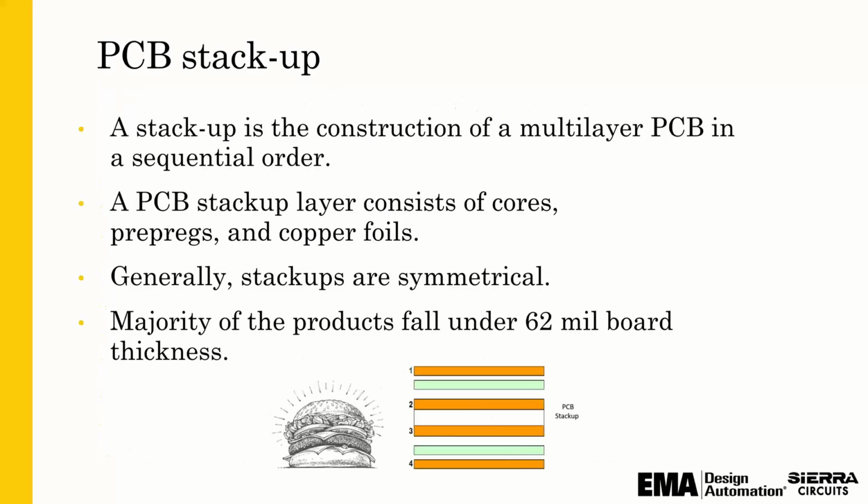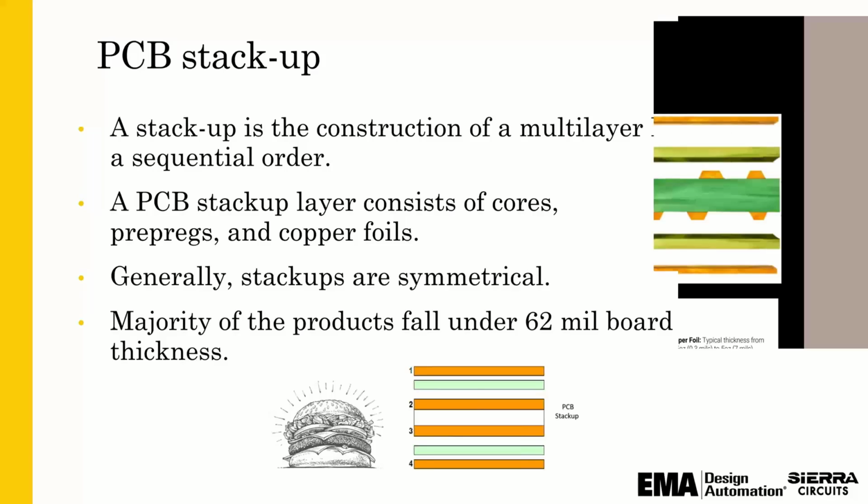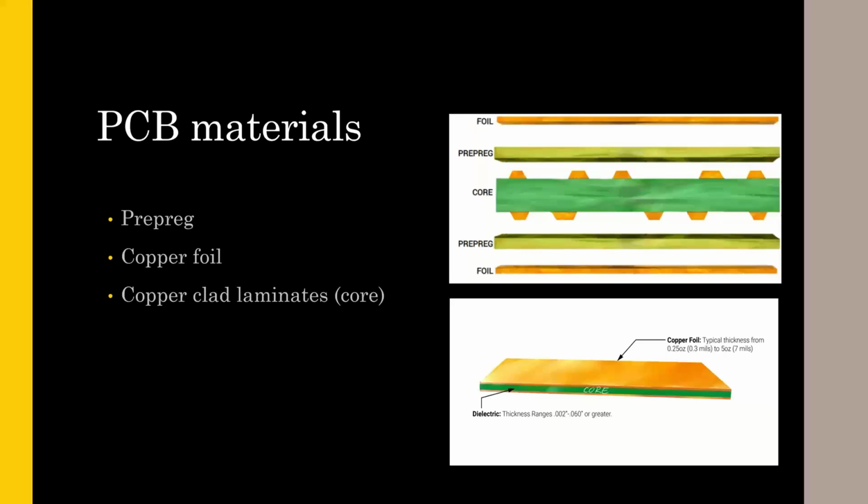Okay, so PCB stack-ups, as far as a manufacturer is concerned, are super important in building a reliable circuit board, in building a cost-effective circuit board, and then from an electrical standpoint as well, building a circuit board that functions the way it's supposed to. So there are some general guidelines. You want to keep your stack-up symmetrical, so that's ease of manufacturing, so it doesn't warp or become a potato chip.